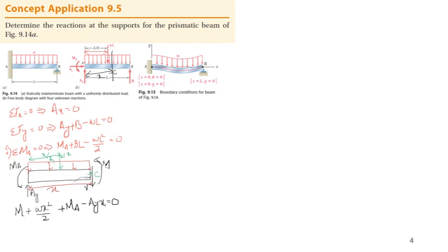So this is my equation of moment, and if I want to write M, it will be AY x minus W x square by 2 minus MA, and this equation will be valid from A to B for the whole length of the beam. Okay, that is the equation.